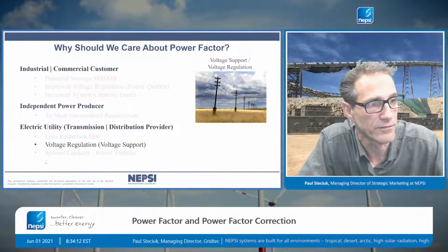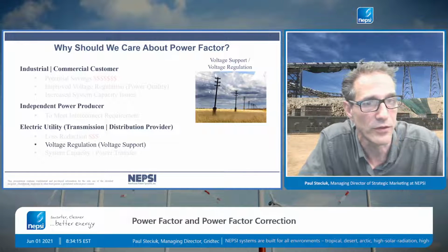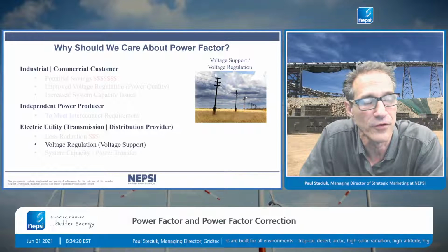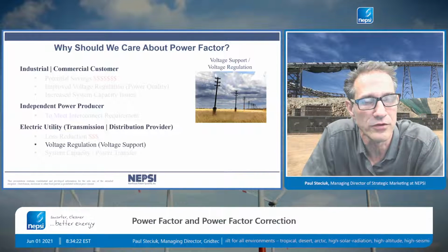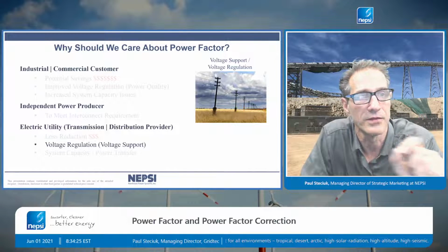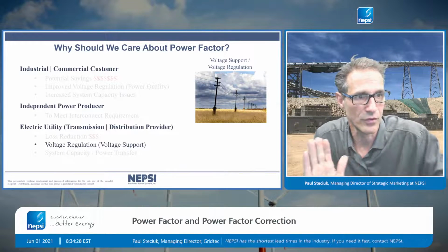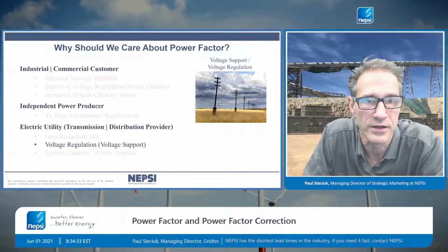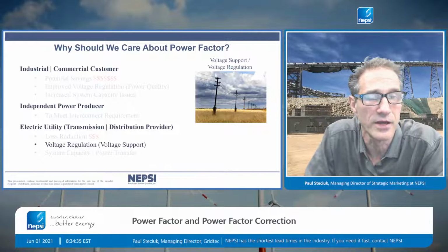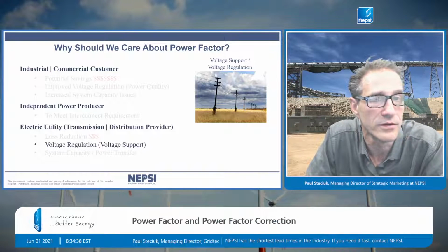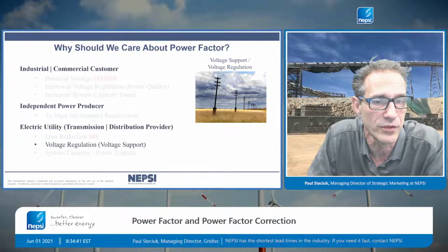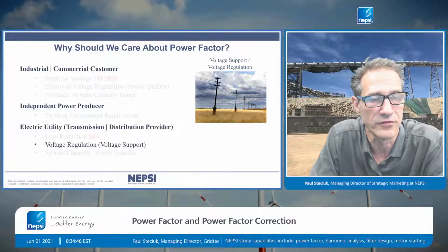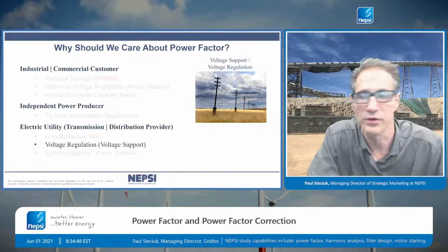They also have long distribution lines, oftentimes 20, 30, 40 miles long. You kind of see one strung here. There is a fair amount of inductance associated with that long distribution line, and then it's I times X. I times X is the voltage drop along that line. That's I times R too, of course, I times R and I times X. But oftentimes X becomes the major component in an overhead distribution line at 13.8 kV or at 38 kV because of spacing, and therefore I have a significant amount of voltage drop along the line.